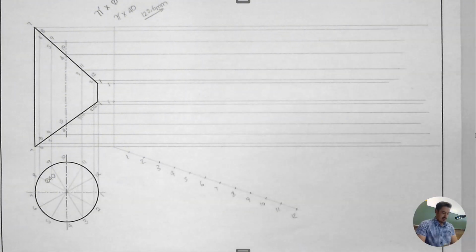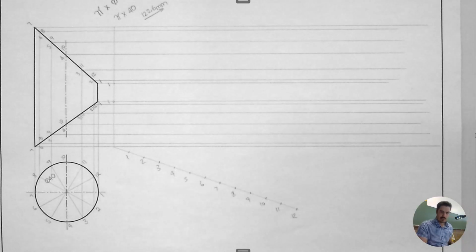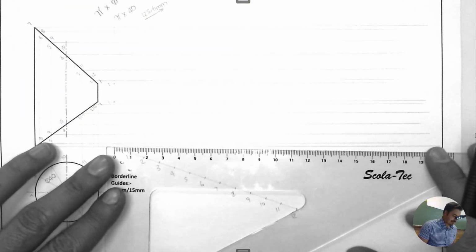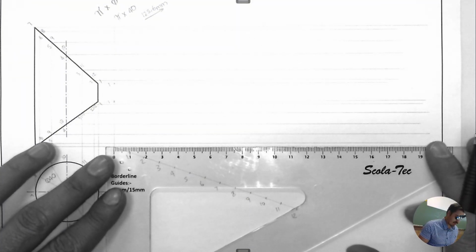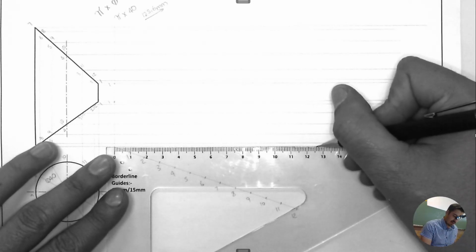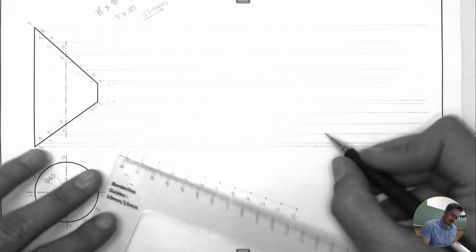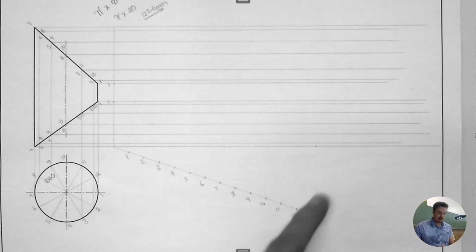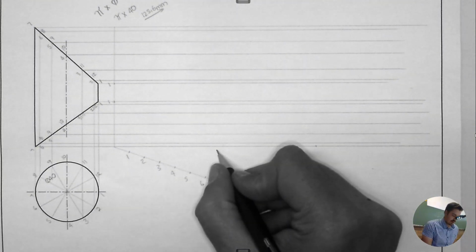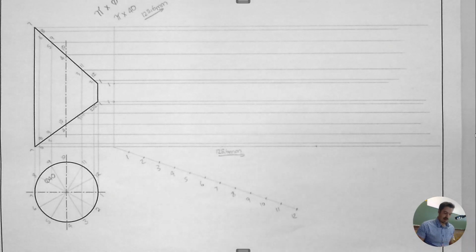All right. So we need to find a place where this last segment can connect onto. So that is why we do this, the pi times 40. So now we have 125.6. In length of your drawing, right? You're going to measure, there's 120, 125. So 125.6 is basically going to be there. All right, so there is the distance, 125.6 millimeters is what I have there.